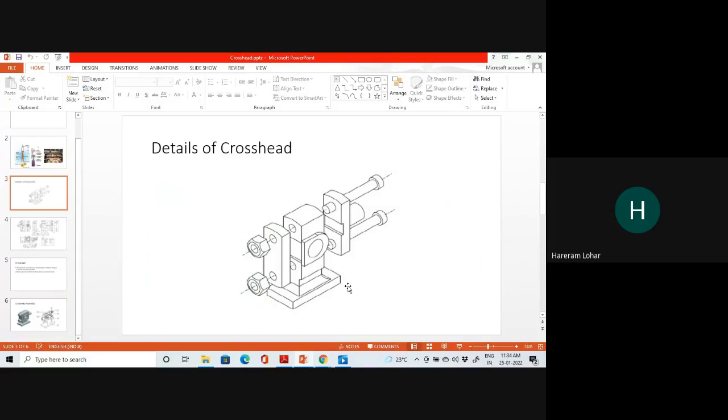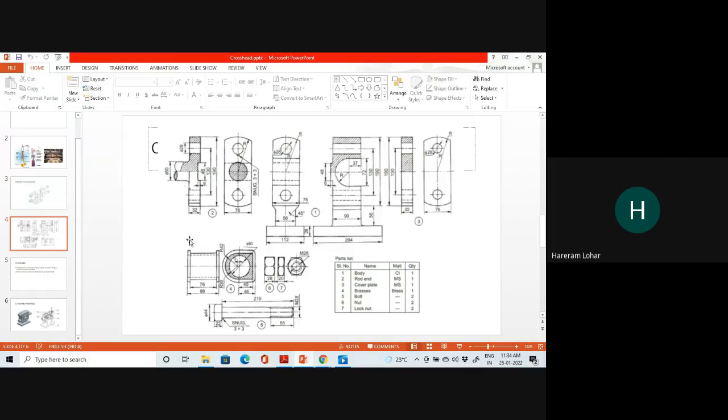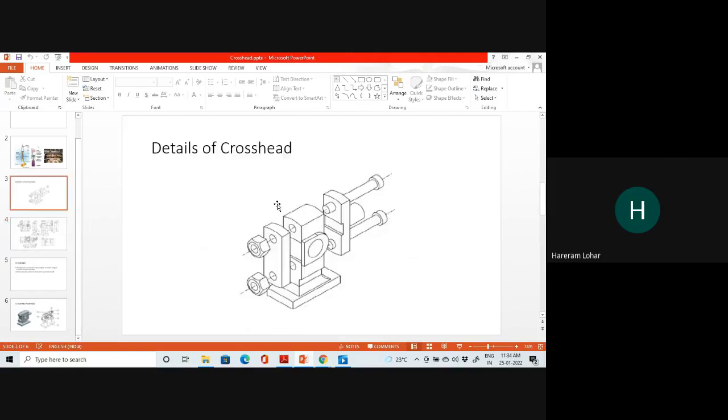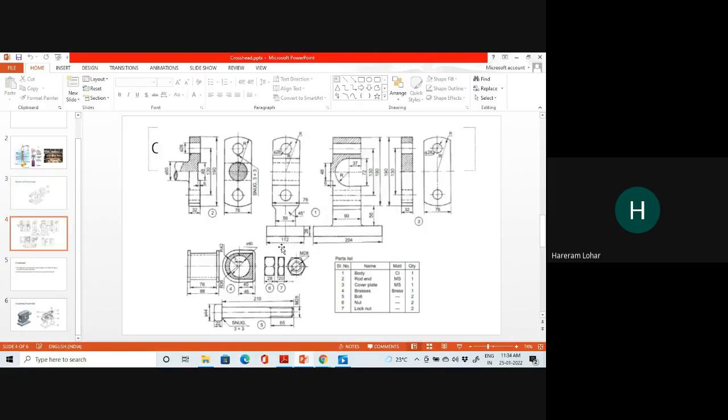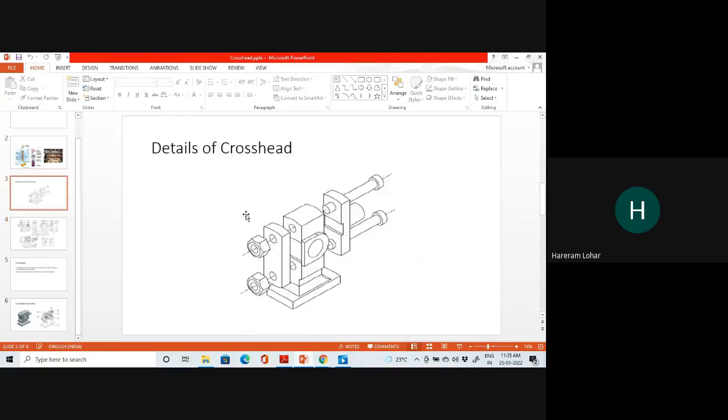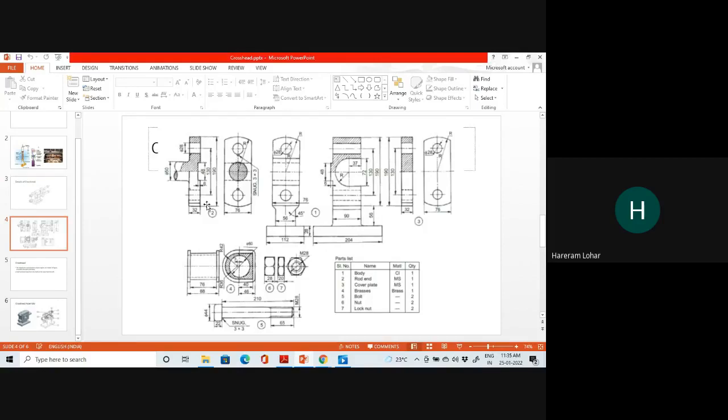So what you have to do, these are all the detail drawings of the components for this assembly. Here the front view and one side view is provided for each assembly. With each component, a minimum of two views are provided, but for the bolt, of course, it will be asymmetric, so a single view will be provided, because the other view will be the same type of view.